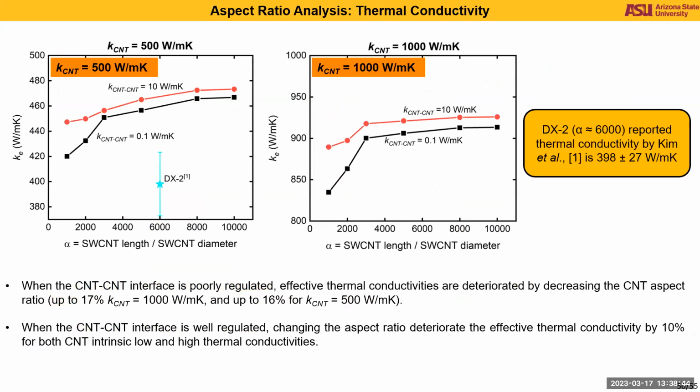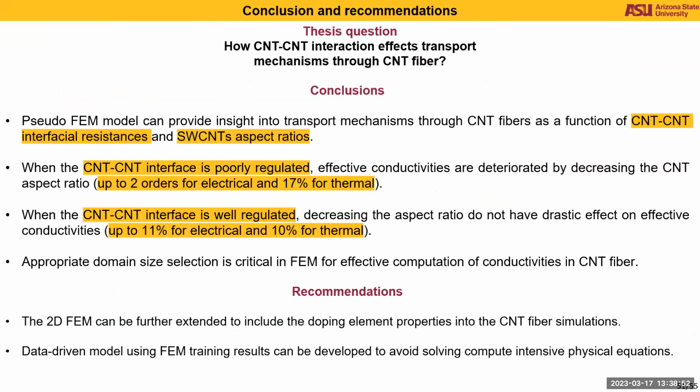In the interest of time, I will just skip it, but the trend for the thermal conductivities is very similar. So to answer our thesis question, how CNT-CNT interaction affects transport mechanisms through CNT fiber, we developed a pseudo 2D FEM model that can basically incorporate CNT-CNT interfacial resistances and single wall CNT aspect ratios.